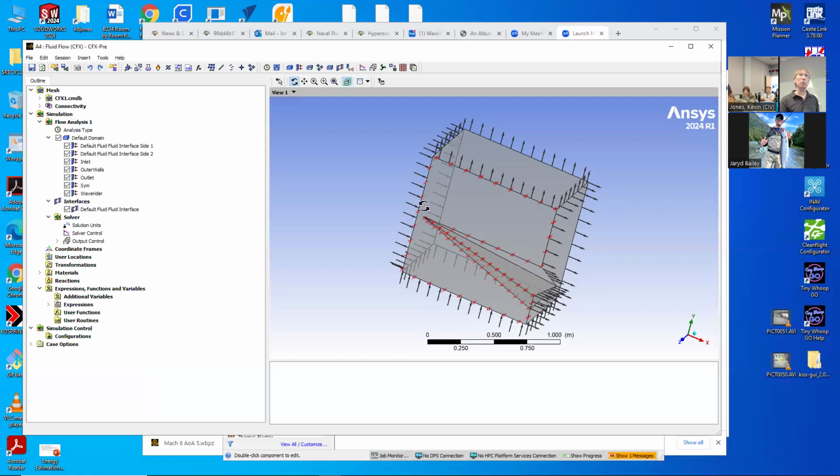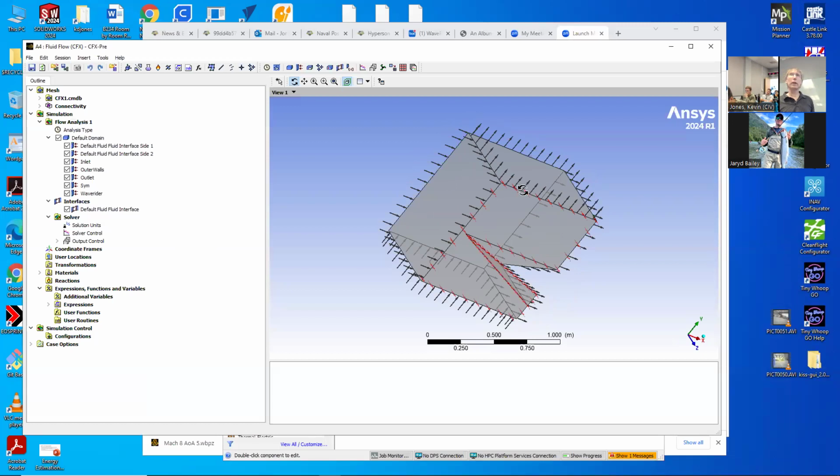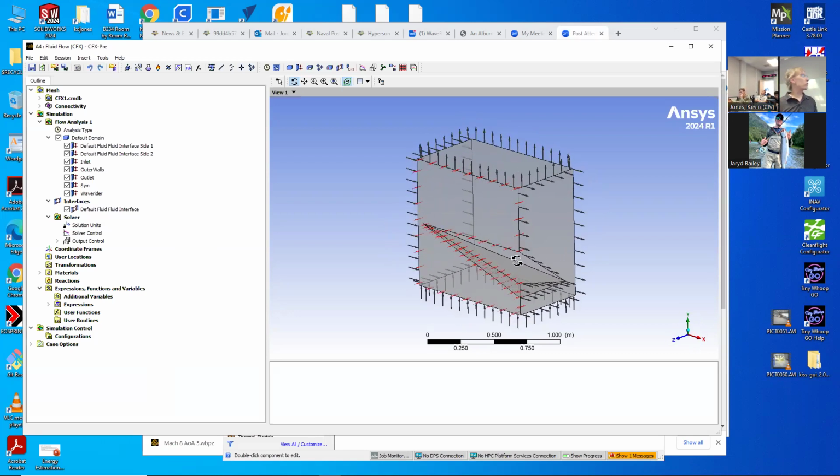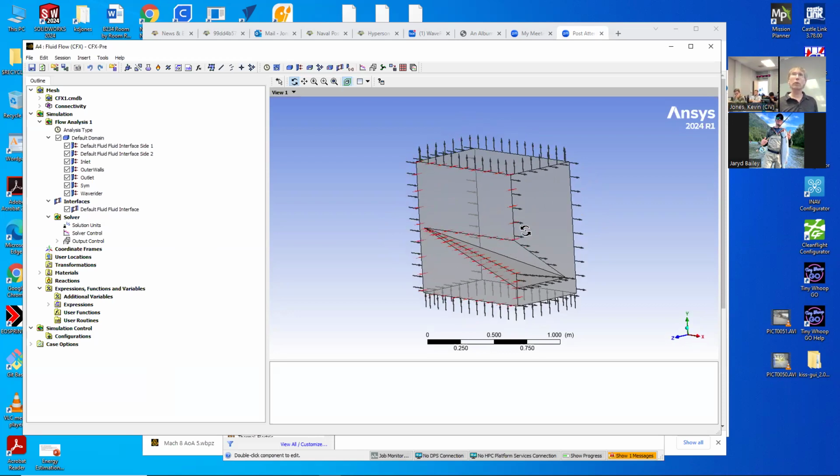I think it's because it's actually treated as a flow variable, even though it doesn't vary. And maybe with homework 5, because we only had one cell and there were symmetry planes on both sides, it somehow worked itself out. In any case, here what ends up happening is that it doesn't set the inlet Mach number correctly, and it starts going through crazy wild swings and blows up. Other things that I tried, which shouldn't have made a difference, but I guess it's worth talking about.